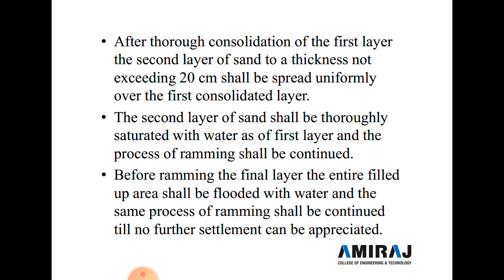So after thorough consolidation of the first layer, the second layer of the sand, of a thickness not exceeding 20 centimeter, shall be spread uniformly over the first consolidated layer. So the second layer of the sand shall be thoroughly saturated with water as the first layer, and the process of the ramming shall be continuously done. So here after applying the rammer, sand is properly compacted.